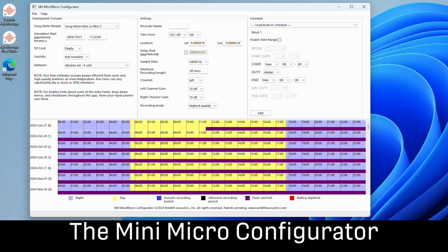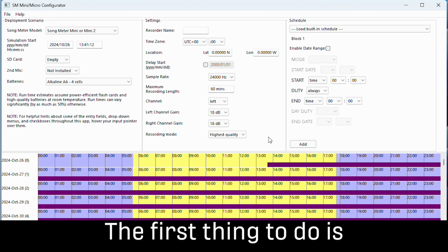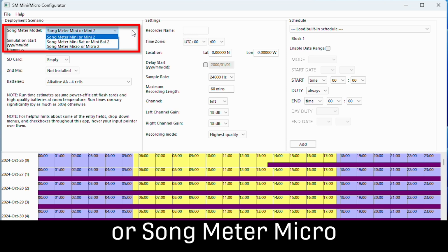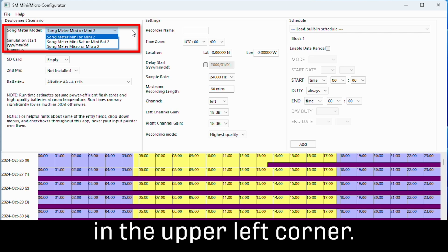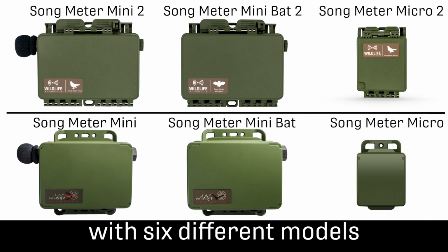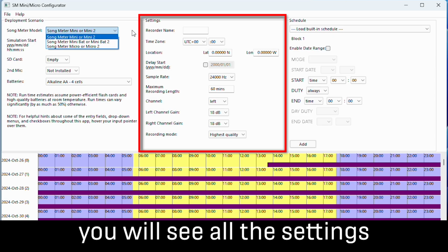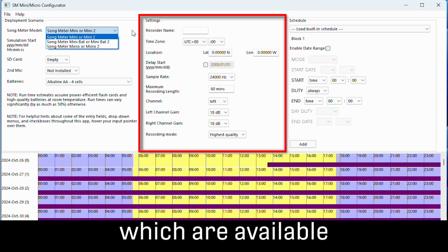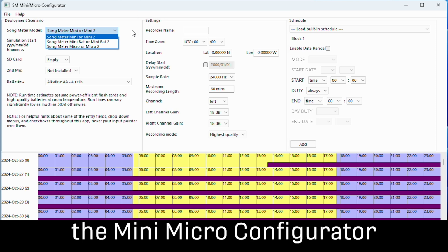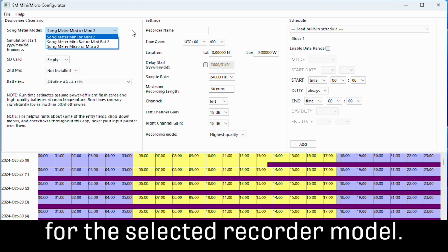The Mini Micro Configurator opens as one simple window. The first thing to do is select the correct model of Songmeter Mini or Songmeter Micro from the menu in the upper left corner. The Mini Micro Configurator currently works with 6 different models of Songmeter recorders. When you choose a model of Songmeter, you will see all the settings which are available for that specific model. By default, the Mini Micro Configurator opens to display factory default settings for the selected recorder model.